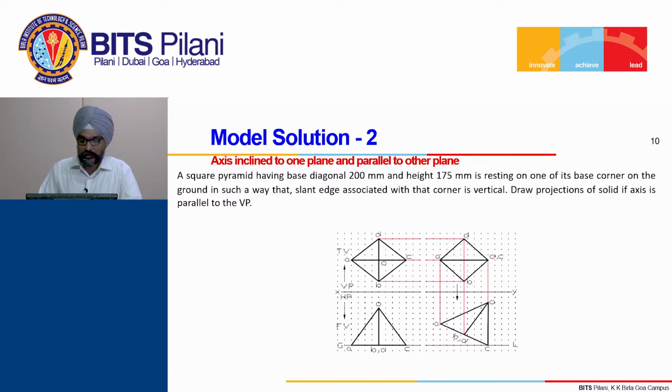So how do we reach this position? That is very systematic. We have to draw the lines from corresponding points in the previous position and in the top view, and the new position front view, and the intersection of those lines gives you new points. Joining the points finally gives us the final shape. So this is the final position, this is the rest condition as defined. We reach here in two steps.